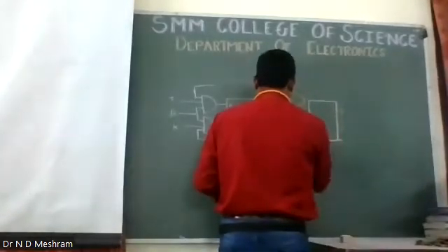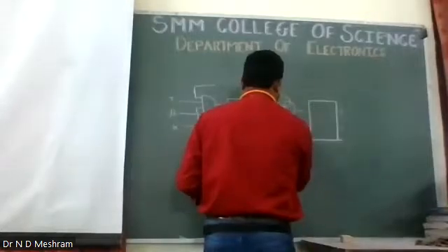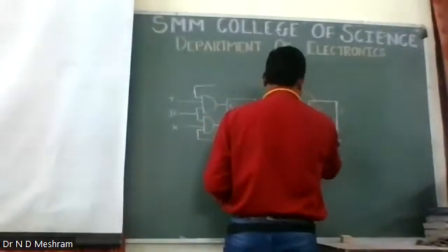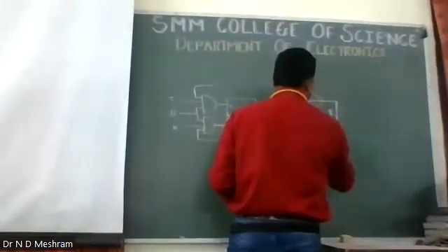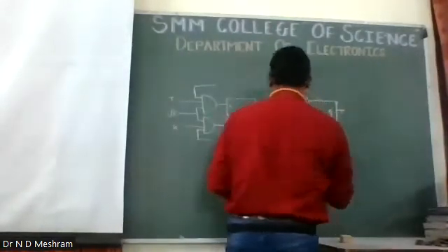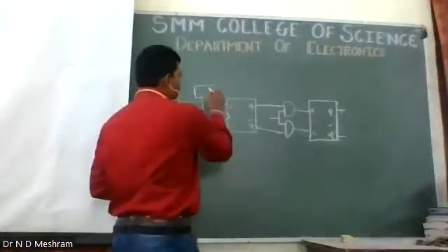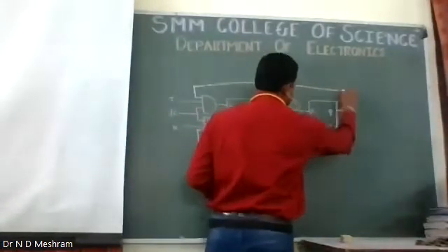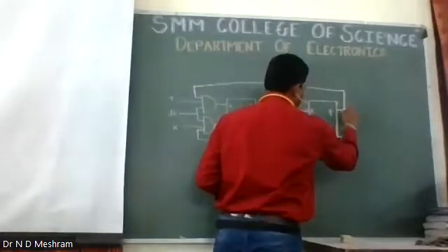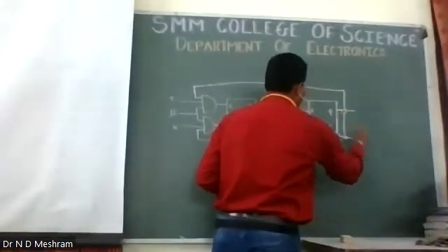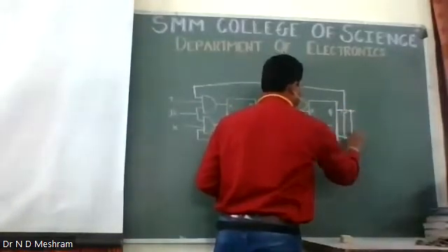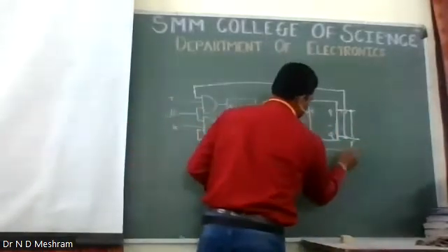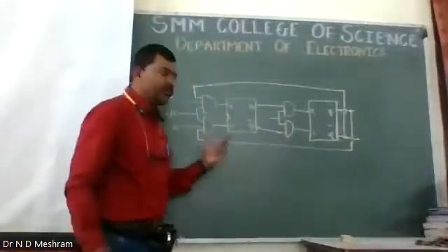Okay. So this is that gate, and these are again R and S. This is Q and Q bar. So these are the outputs likewise. So this input to this AND gate is now fed back with the output of the last, that is the Q bar, and this output of Q is fed back to the first input, as we have done in the JK flip flop.